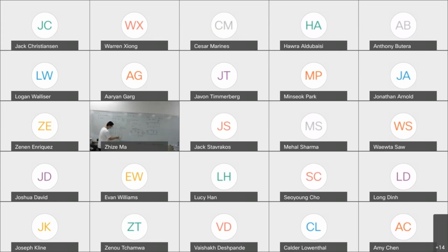Also the function: when you measure an AC signal, you will need to turn the dial to the voltage symbol with a wave. I think the logo is something like this. That means AC signal. So when you measure an AC signal, it's a different setting from a DC signal.